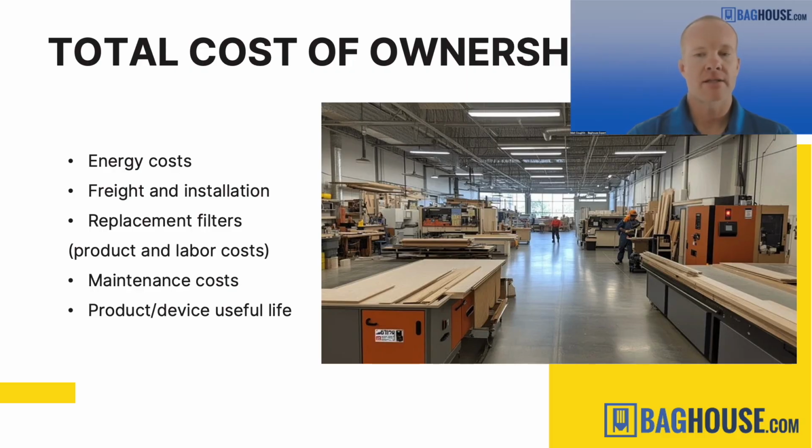Product and device useful life. So a properly designed dust collection system for a wood shop should last for many years, decades, without having to replace any of the major components. A lot of this is going to depend on ensuring that it's designed correctly up front. So correct sizing, correct motor sizing, velocity through the ductwork, all these types of things, as well as making sure that it's maintained. So changing your filters when they require it, making sure that your pulse cleaning system is well maintained, diaphragm, valves, timer board connections, solenoids, all these things are replaced and maintained properly to make sure that your overall cost of ownership is lower.